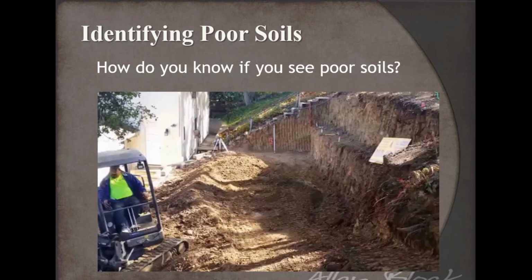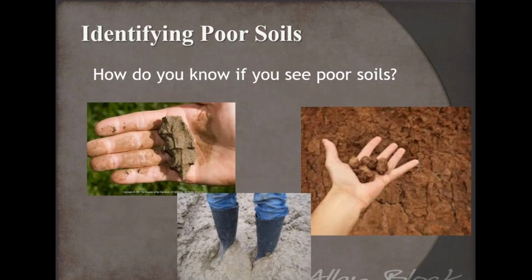So, like I said, how do you know you have poor soils? I wouldn't say that this is a red flag, but you definitely know you've got cohesive soils, which means you've got some water sensitivity going on in soil conditions like this. There are some little things that you can look for. Obviously, we always say grab a handful of that soil, and I'll get more into this as we get to different classifications. But since clay seems to be what people center on, there are different states of clay, and we'll get into more of that when we actually do the testing.